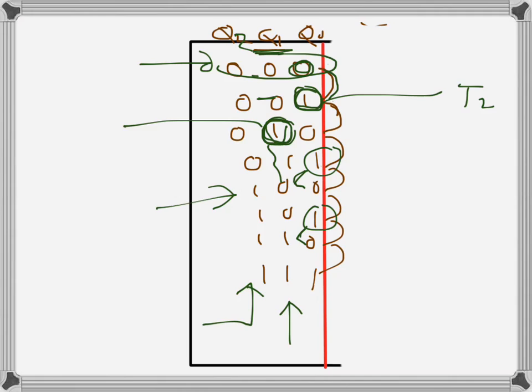So what is the significance of this one? Here both Q1 and Q0 are 1s. Similarly, here both are 1s. So only when both Q1 and Q0 are 1 should the most significant bit toggle, because that's what actually happens when we are counting up binary.